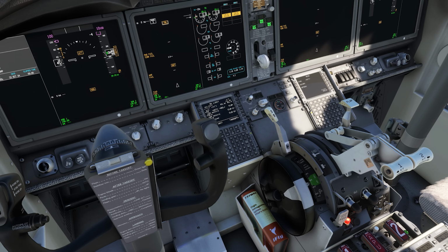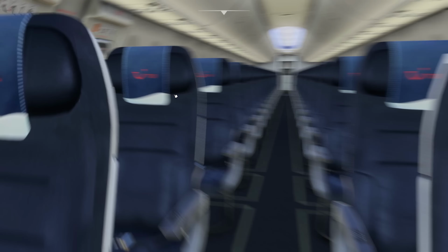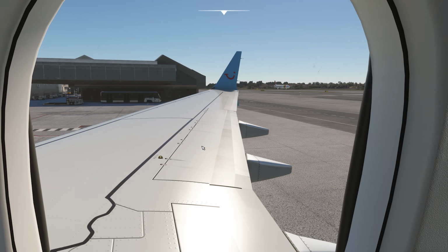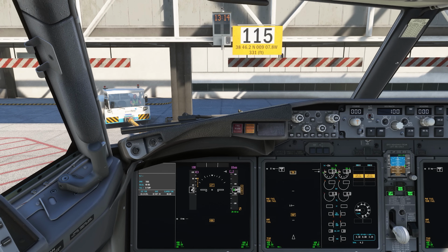One of the neat features as well, if you're a passenger on a MAX, you might notice on short final the speed brakes deploy maybe just prior to touchdown. Now this is something called LAM, or Landing Attitude Modifier. Basically due to the way the MAX flies and these large engines, it would approach naturally quite flat. We want to make sure we have a slight nose up attitude on the flare to ensure that we touch down on the main gear. What happens is when you select the landing flap 30 or 40, it will automatically deploy a little bit of speed brake to ensure that the main gear touches down first, and again that is transparent to the flight crew. The speed brake lever won't move.